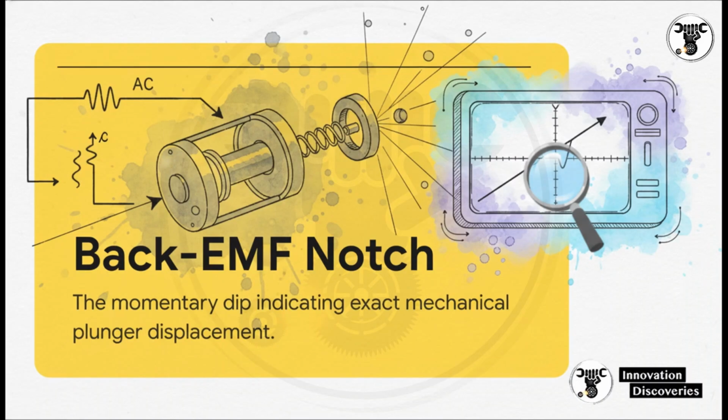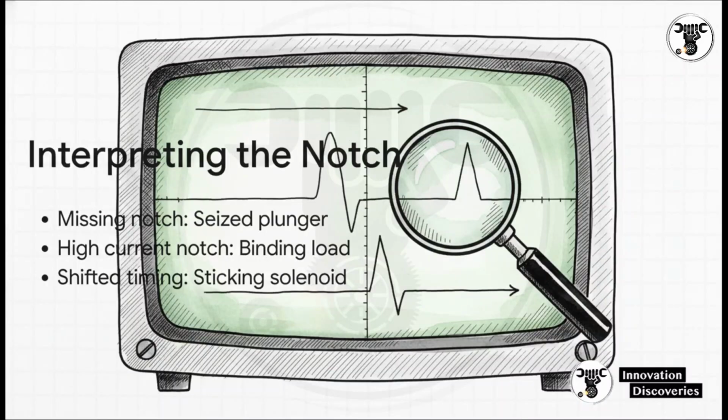As a master tech, here's exactly how you read the matrix. If you look at the waveform and that notch is completely missing, the plunger is entirely seized. It never even moved. If the notch happens at an abnormally high current level, the plunger is binding up or facing excessive mechanical resistance. And if the timing of the notch is shifted compared to OEM spec, you've got a sticking solenoid. See, the electrical circuit is technically intact, which is why your code reader passed it, but your scope just proved the mechanical part is failing.